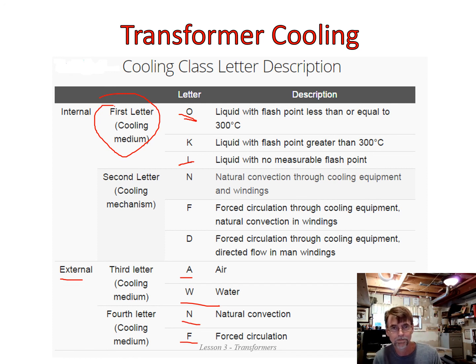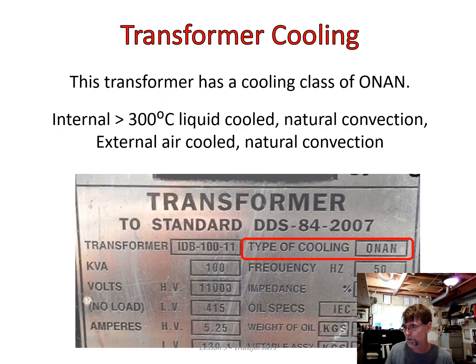Cooling of a transformer is a really big deal because primarily that's what it does. It's not going to break because of moving parts. It's going to break because it overheats and the insulation around the coil gets compromised. So heating is the issue, so cooling is important.